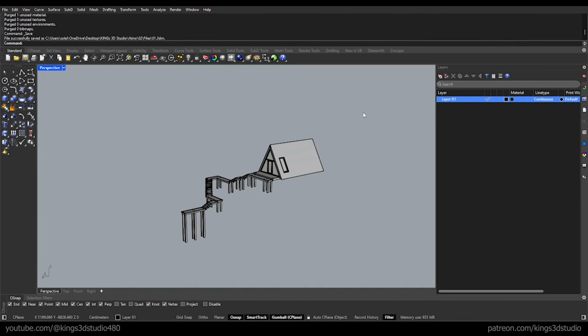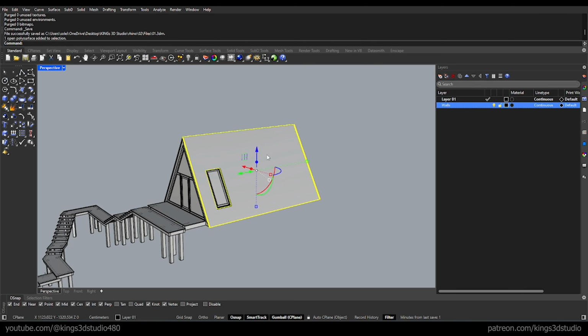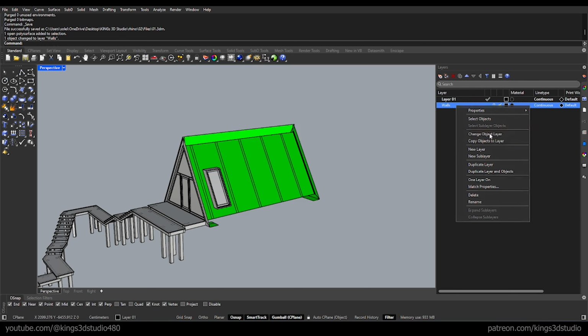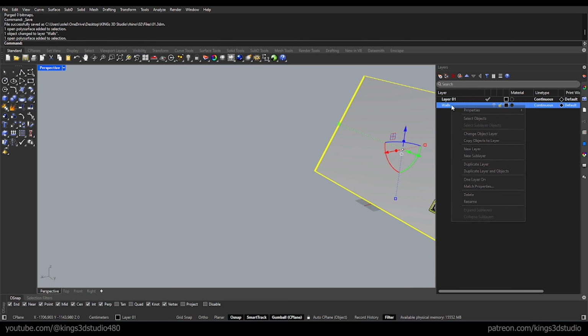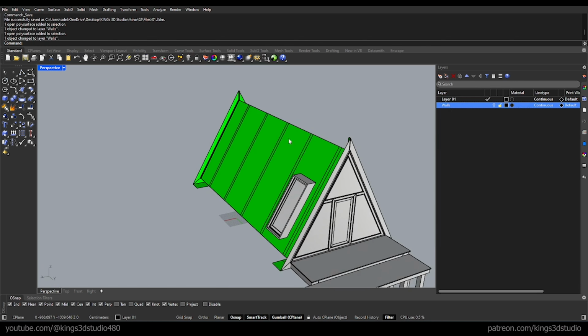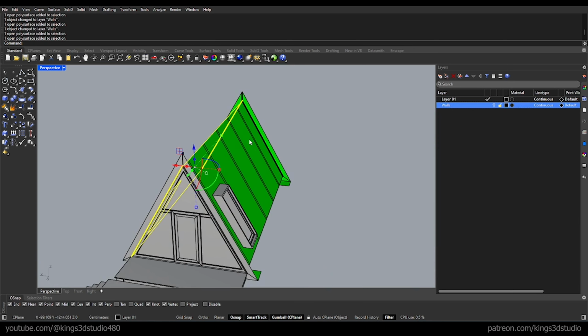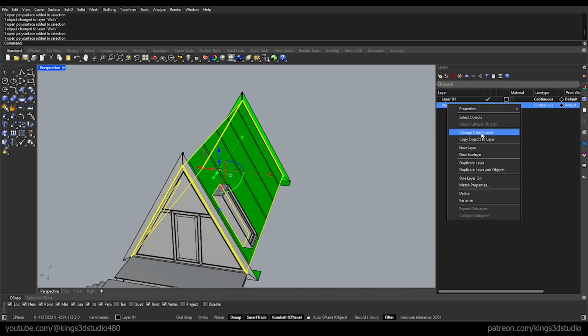For different objects in the scene that we know will have the same material or different materials, we have to assign a material here in Rhino, so Lumion could recognize it as a separate object, so we could assign them separate materials later on in Lumion.